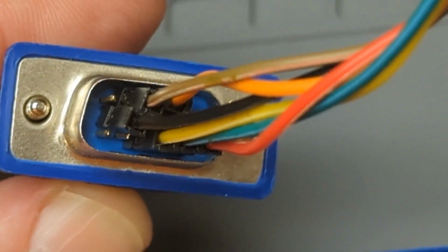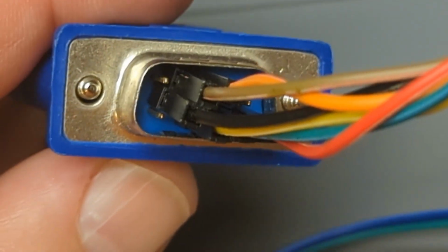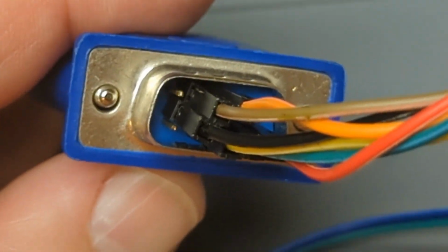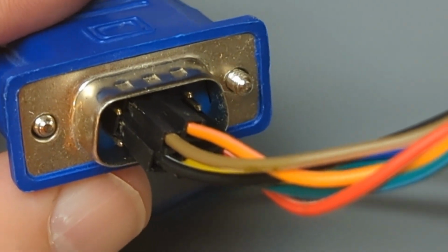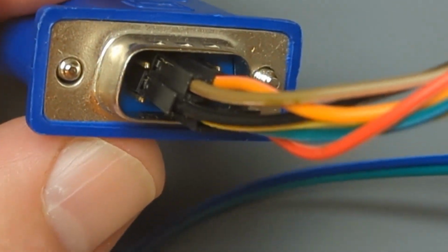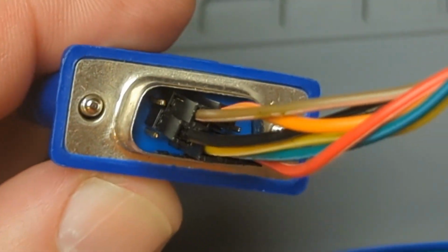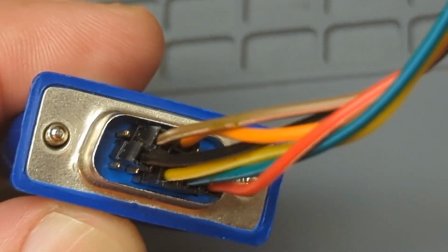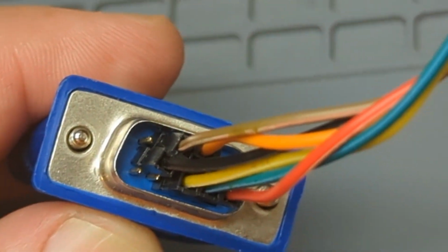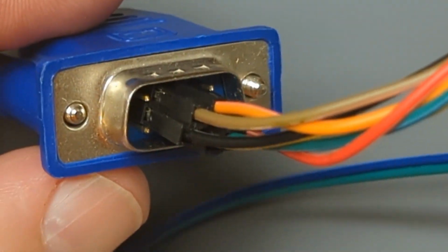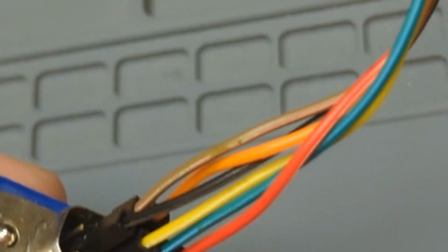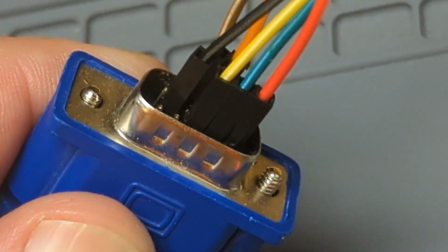These pins are physically smaller than the ones on a DE9, and those little square ends that you get with your breadboard kits fit very nicely on the pins in there. If you shove that onto a DE9, it won't really fit, and if you force it, it'll get stuck and destroy the square end on these cables. I'm just saying. So this is how I made my breakout cable.